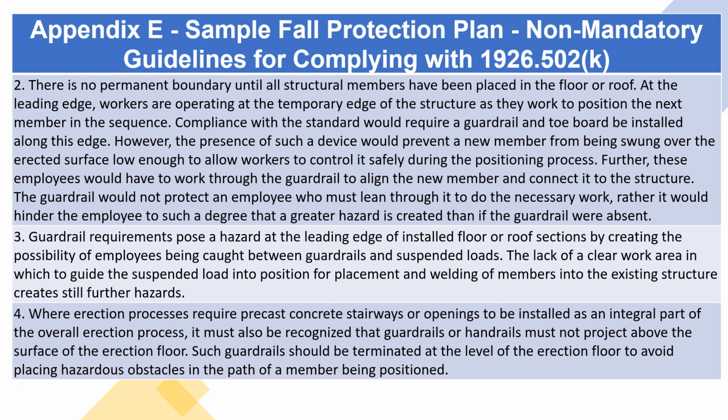2. There is no permanent boundary until all structural members have been placed in the floor or roof. At the leading edge, workers are operating at the temporary edge of the structure as they work to position the next member in the sequence. Compliance with the standard would require a guardrail and toe board be installed along this edge.